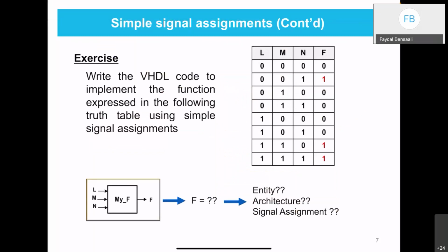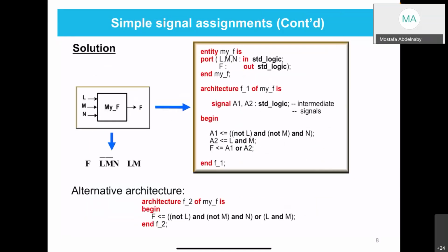Let's say that we have this circuit, we gave you this truth table, and we ask you to implement this circuit or to describe the circuit using VHDL. Is this clear? So the next step you do, you can just do K-map and you guess the expression, right? You know how to do this, right? You do K-map, you guess the expression. Are you still with me? Yes, doctor. Okay, good. So I did K-map, I didn't put the K-map here, and then this is my expression. Once doing the K-map, we just describe the circuit.